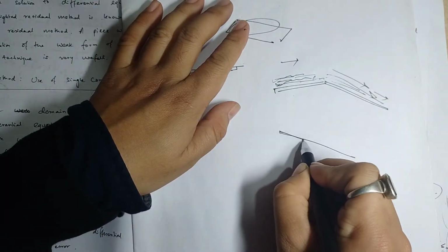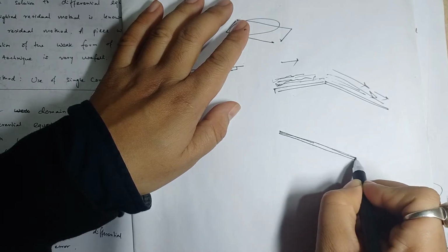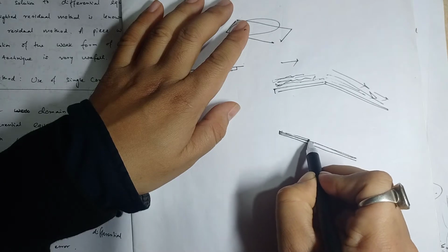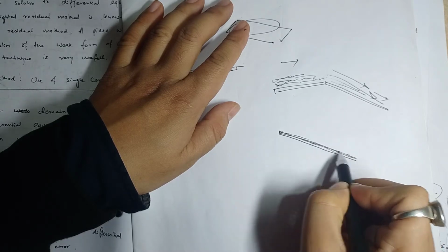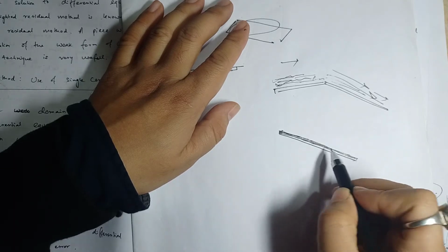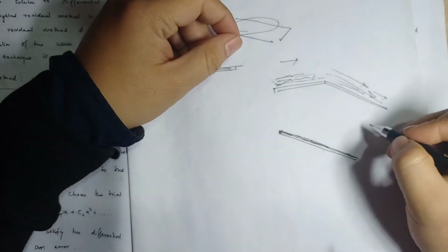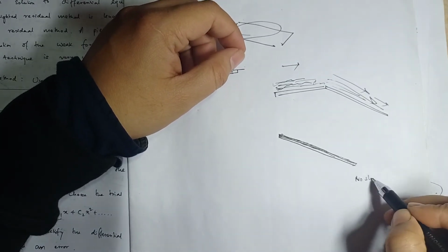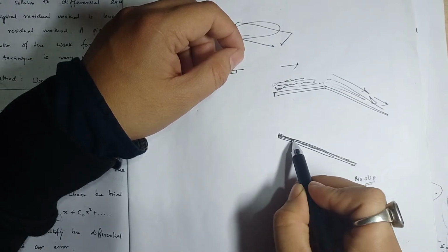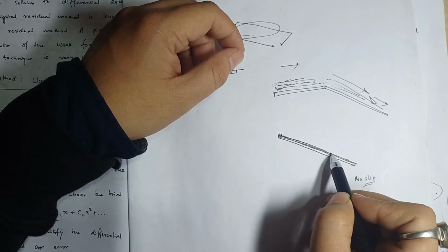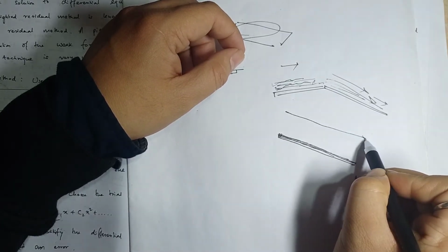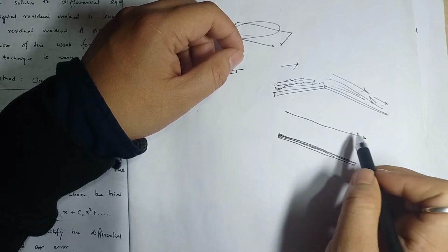This is a laminar flow, obviously, so turbulence is not there. The fluid layers which are touching this surface are almost stagnant. They are actually not moving. There is a condition called the no slip condition, and due to it the layer adherent to this surface is not moving, and the uppermost layer is moving at the highest rate.